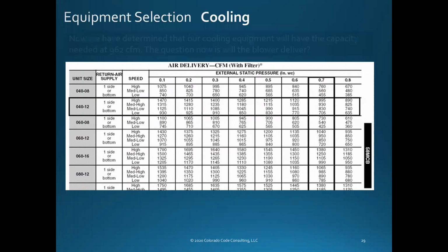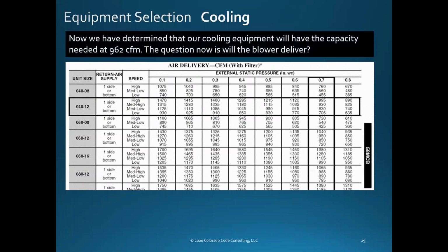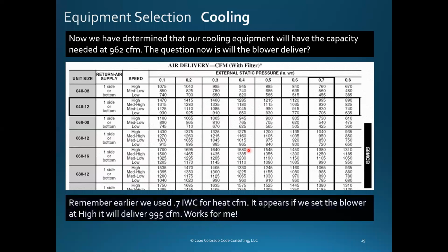All right, so we're looking at our fan flow here. Really, can we get it? Well, yeah, we can get this 995 in here. No big deal, sure, we can do it. Designers will not want to do that. Designers are going to say, I need to be able to go up a speed, especially at altitude. I'd rather try to get my paperwork and everything down at the medium high and not try to push the envelope there. Hence the need, right?